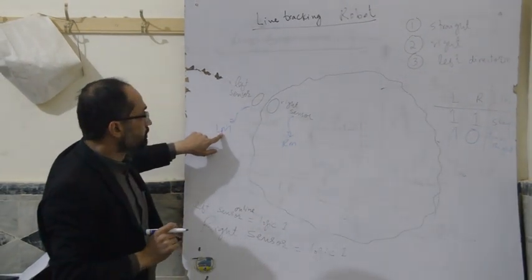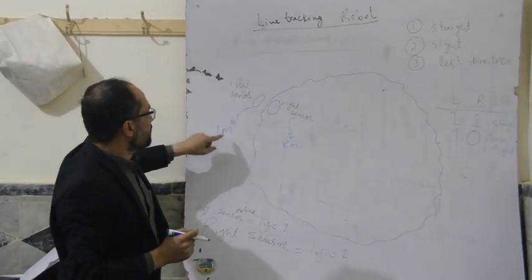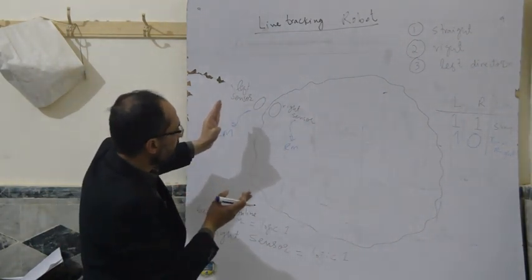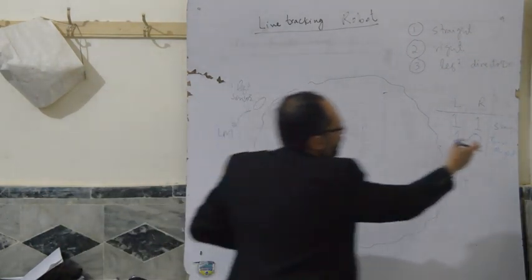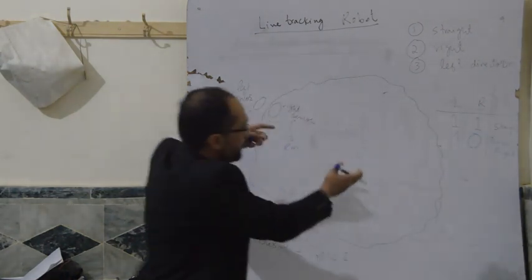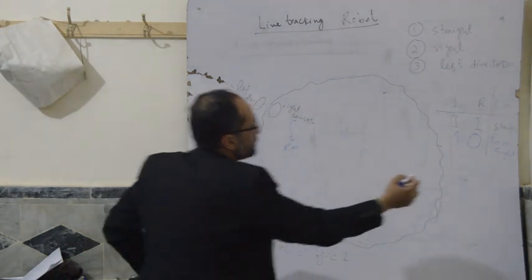In this scenario, the left motor should be stopped and the right motor will be on. So in this case, it will turn right, so that both sensors are on the line.